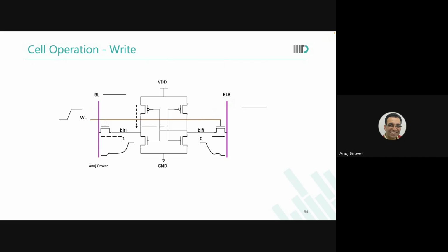Yeah. So what happens? Even if the inside was not supposed to flip, you have discharged the bit line. And in what you are suggesting, you will actually read all the bit lines now. Otherwise, you discharge one bit line a little extra, which was not needed. So it doesn't really help much from where I see it. But in a very specific, very, very low power architecture, you might put in some design techniques where it could help. So we can look at that later.